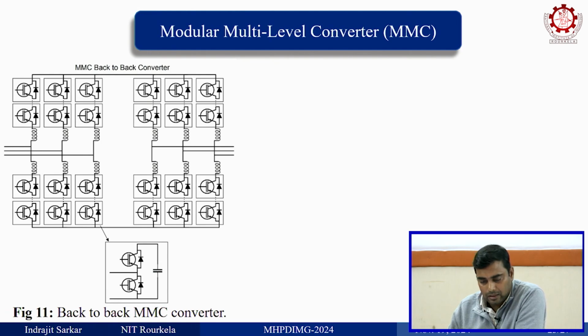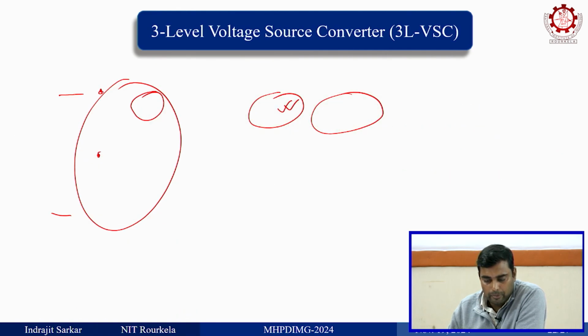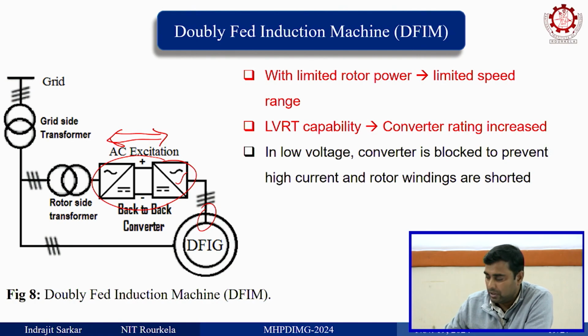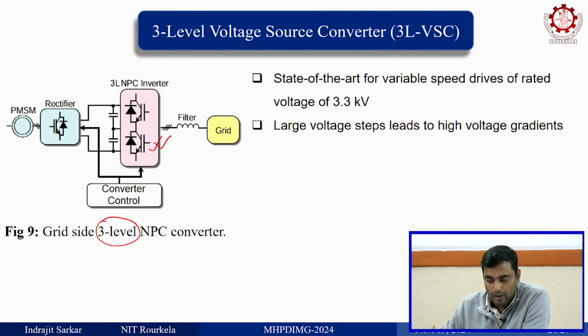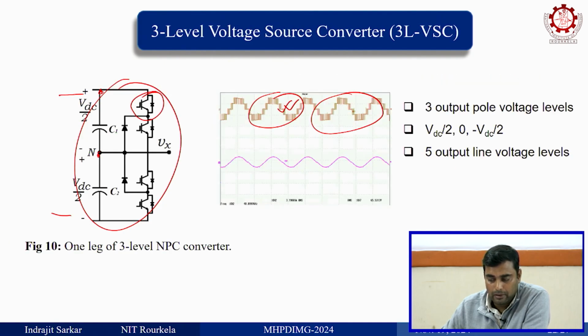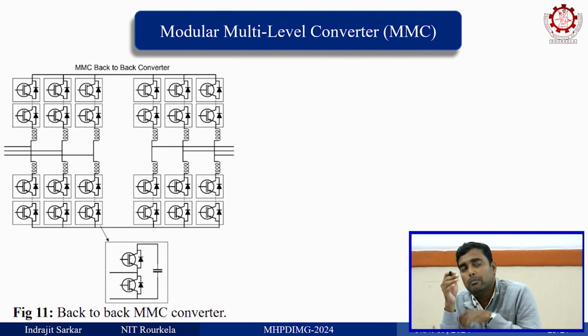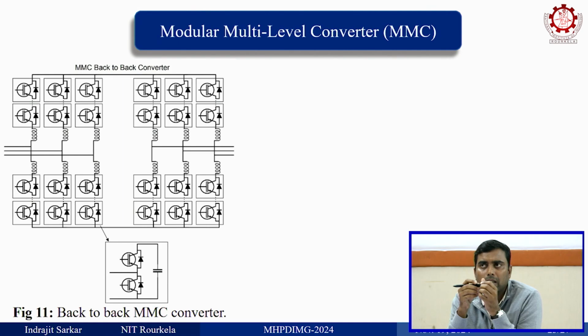Another thing is, here in the back to back converter, depending on the voltage level, you can use a multi-level converter in order to cope with the increasing voltage level. Or one of the very popular multi-level converters, now very popular in HVDC application. Almost every HVDC application, every DC application is using this converter. It is the modular multi-level converter. Okay. You can see on the internet, there are many companies in China and all over the world that prefer this converter and are implementing it.